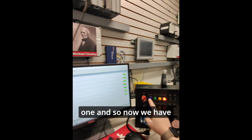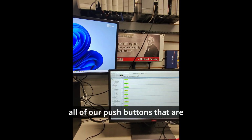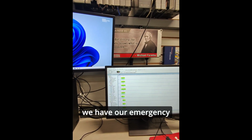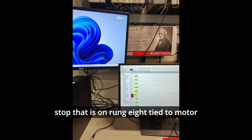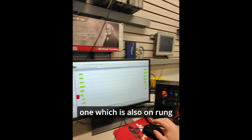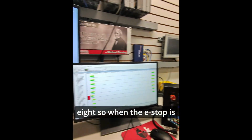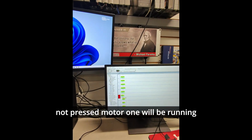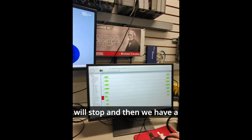And so now we have all of our push buttons that are addressed on rung 0 through 7. Then we have our emergency stop that is on rung 8, tied to motor 1, which is also on rung 8. So when the e-stop is not pressed, motor 1 will be running. When it's pressed, motor 1 will stop.